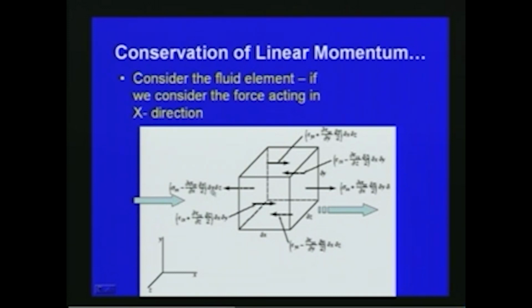The surface forces can be the normal stress or the shear stress. With respect to the normal stress, for this particular fluid element, in this direction on this face of the fluid element, since the x direction is like this, it can be written as sigma xx minus del sigma xx by del x into delta x by 2, multiplied by the area of this face of the fluid element, delta y delta z.